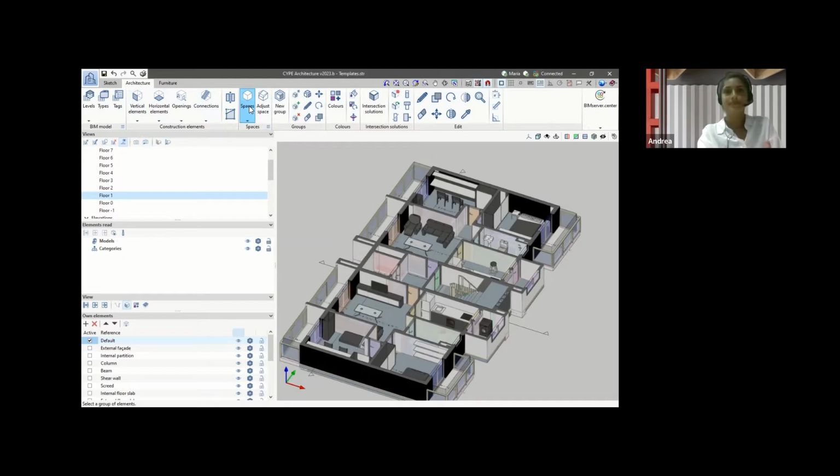This is important because of the ability this program has to create spaces that will be used in other programs, for example acoustic programs, thermal analysis programs, etc. The spaces are very important, and this program has some tools, especially this one, the detect spaces on plan. I think it is particularly good because by clicking on just one point of the space, it is detected automatically.